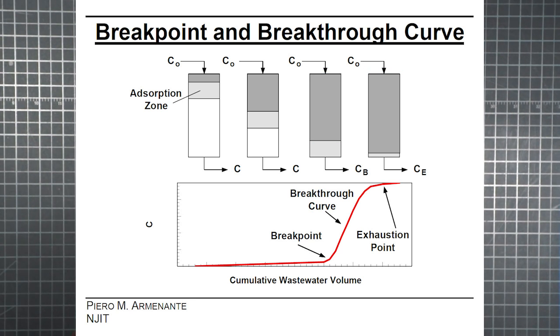The filter is getting used up, but it's aging gracefully so far. The outgoing water is still being reduced to near zero impurities. But the feed must travel farther and farther before encountering the portion of the bed that has not yet reached equilibrium. That means the light gray zone where adsorption occurs is effectively moving its way down the length of the filter. What happens when it finally reaches the bottom?